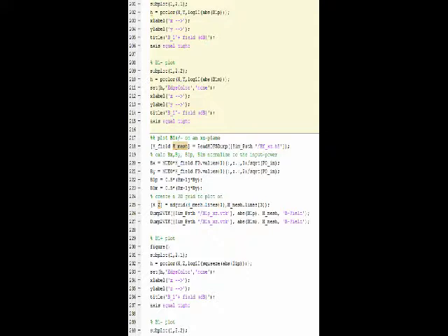From now on, we're going to plot B1 plus and minus on the XY plane and the XZ plane as well. From the first line, we have the magnetic field and magnetic meshes using the function read HDF5 dump to calculate the BX, BY, B1P, and B1 minus, normalizing the input power as we mentioned.